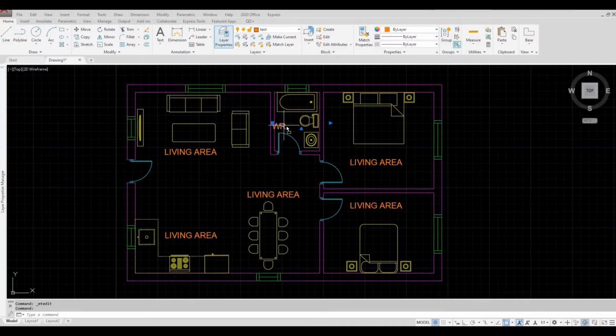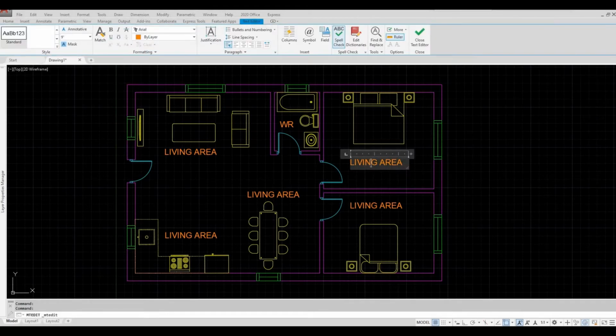I'm gonna grab it and hold it so that I could estimate the area. I'm gonna change this by double clicking. I could control A to select everything and then just type bedroom 1 and then press enter. Actually, you just need to click outside.